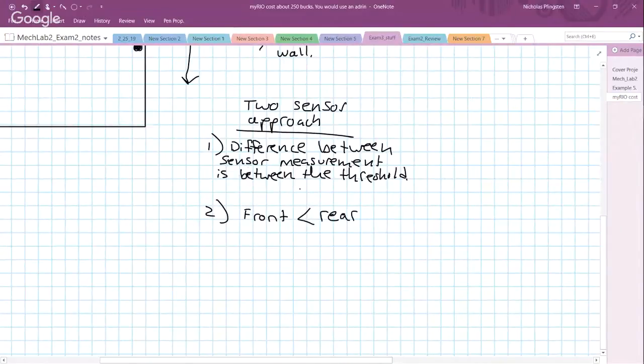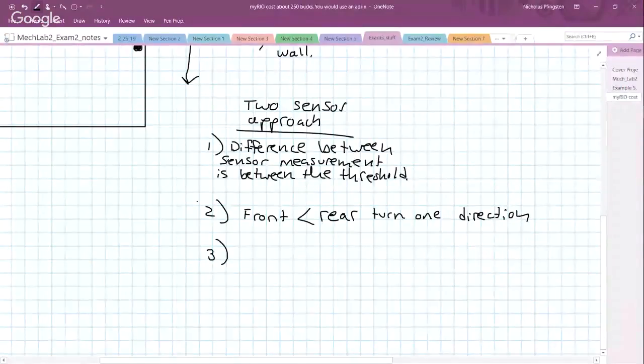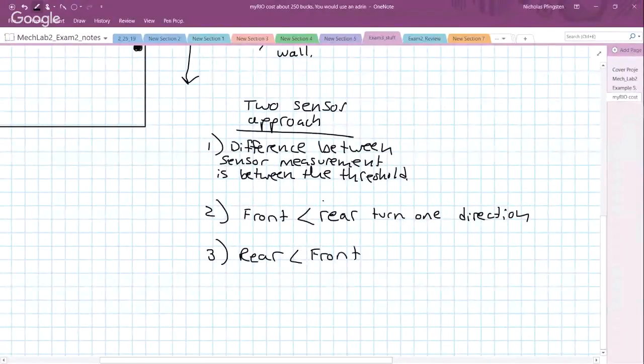So depending on your preference here, the two-sensor approach can be useful. It can give you a little bit more reliability from our sensors. You get a little more reliability looking at the difference between two sensors. But the one-sensor approach is perfectly fair game, and in fact, it can be deployed very effectively, because all you're looking at is the distance to the wall.